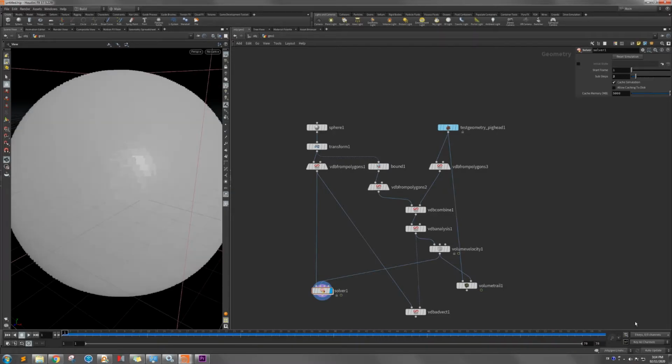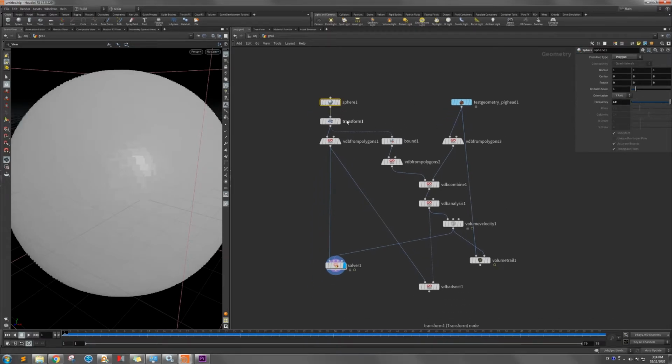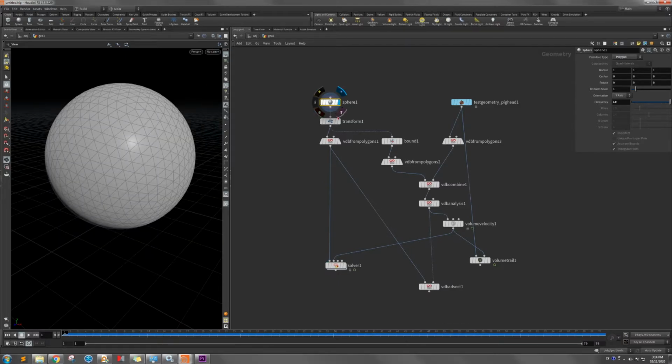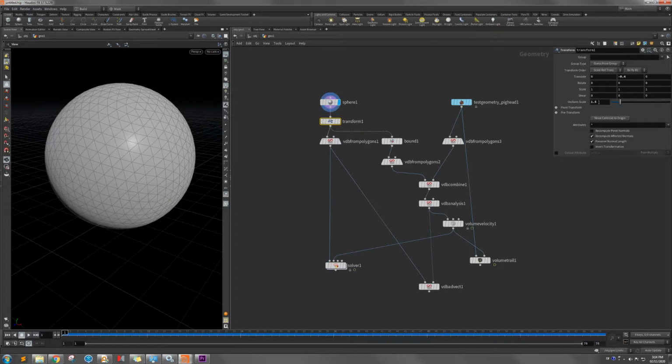Okay, instead of shrinking from the object to a smaller object, we can also do the opposite. From a small object, grow to another shape, a big object. Let's do it. So we just change this network. First thing is we need to make the sphere smaller, probably 0.5.